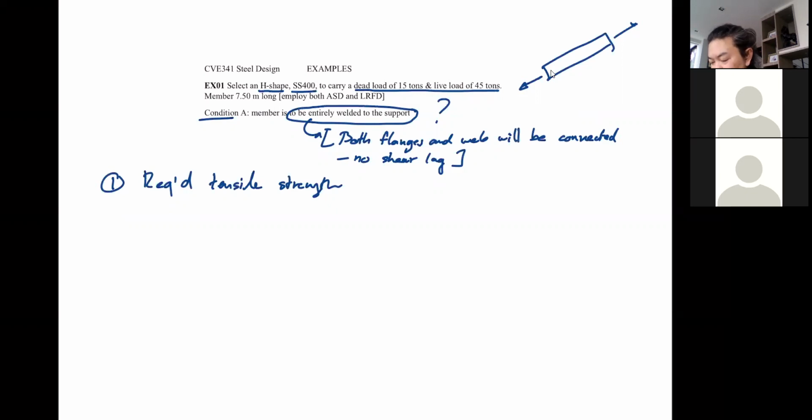So let's say we are going to calculate the load combination. If you have only dead load and live load, so if you check the load combination, which you should, if you have time and do some self-study, we only have 2 load combination cases. The first is total dead load. The second is dead load and live load. Okay, so no brainer that the dead load and live load case should govern.